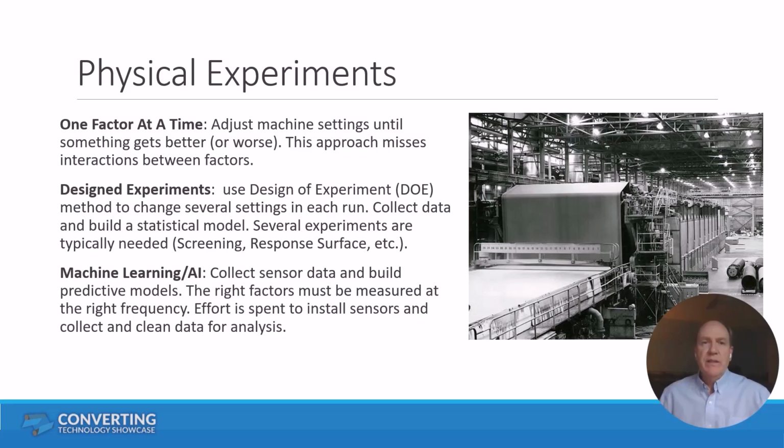Some people will use designed experiments. These are statistically designed experiments, where you change multiple settings in multiple runs of the machine. You collect data from the outputs of interest, and then you build a statistical model, usually some sort of regression model relating the inputs to the outputs.